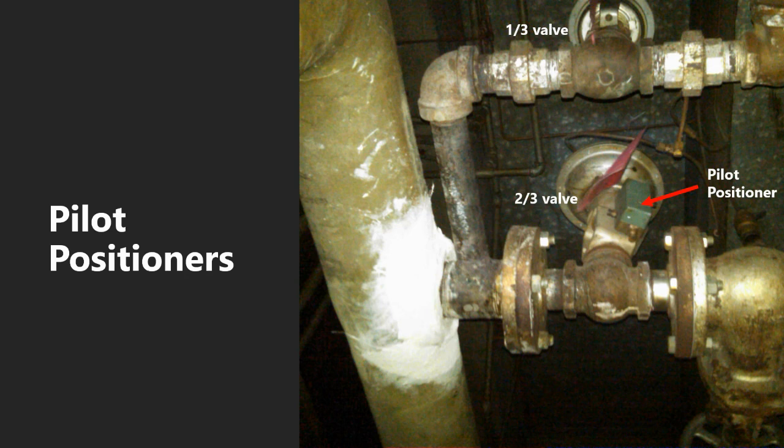Here, though, the pilot has been abandoned and the control signal is now split to feed the two valves exactly the same signal. In a steam system, this can make it very hard to achieve good control when under light loads, as this system will likely end up hunting and cycling excessively, and ultimately prematurely wearing and damaging the valve seats.